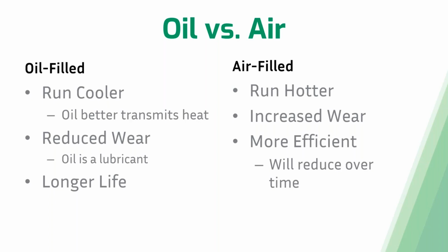Whereas with air-filled motors, these tend to run hotter inside the pump, and this also leads to increased wear of those pump materials. Since you don't have that oil lubricating those materials inside of that pump, those components are going to fail much faster.